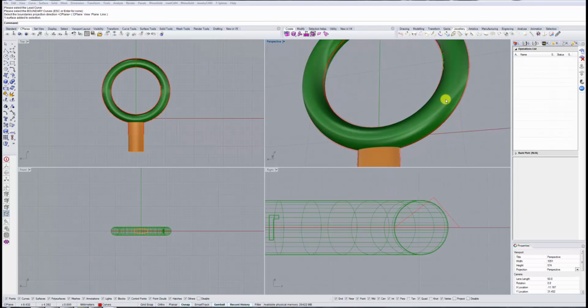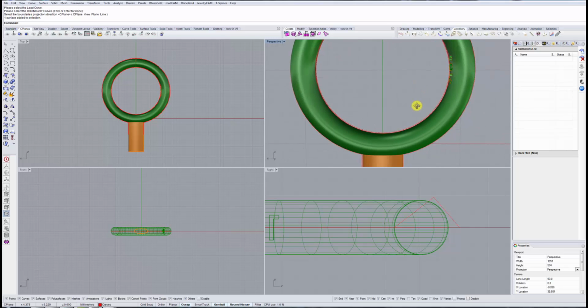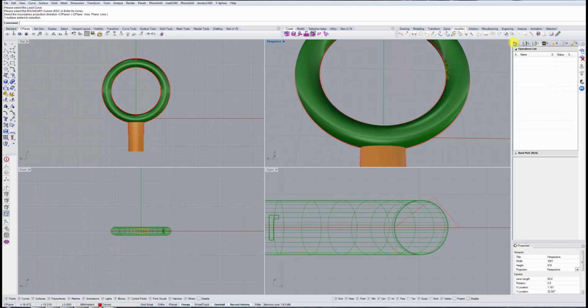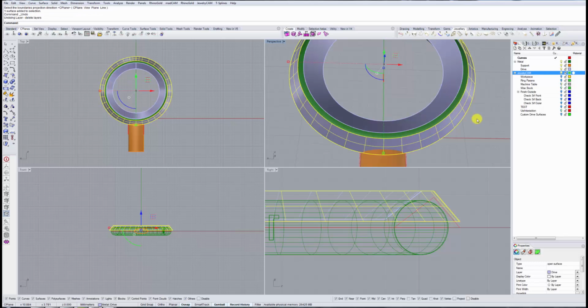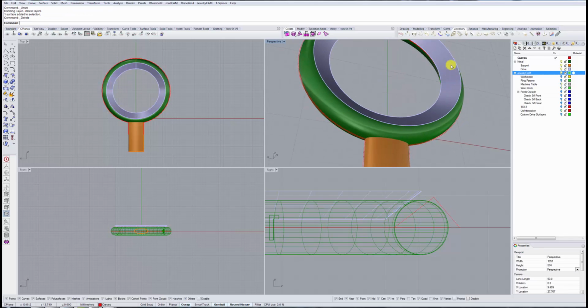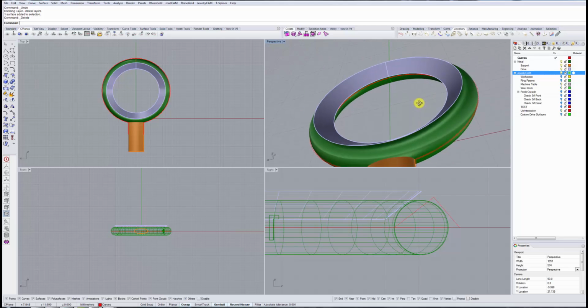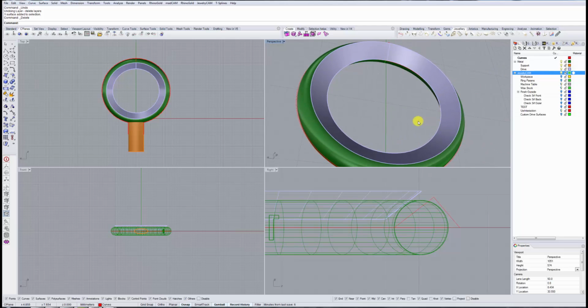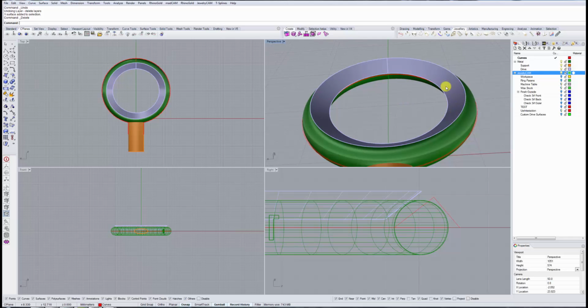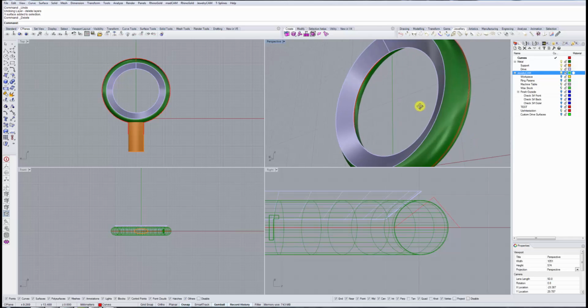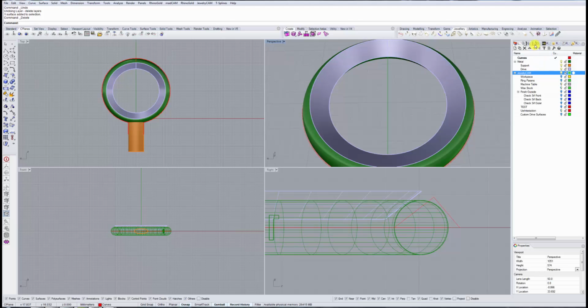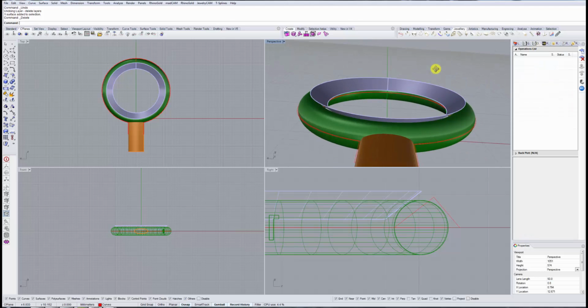Now, to get full appreciation of the power of drive surfaces, we need to look at ones that do not lie strictly in a planar, flat way. So, for example, if we have a drive surface that looks more like this, curved inwards, we can do a nice cut involving all 5 axes while targeting the inner part of this ring. Let me show you how this is done.